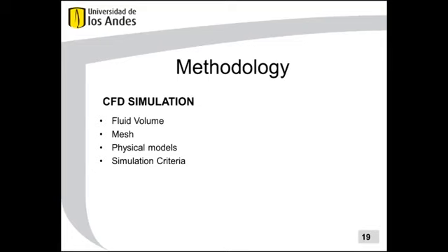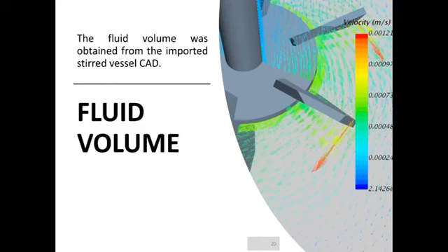Simulations were carried out in STAR-CCM+, a computational fluid dynamics software. The setup consists of specifying the fluid volume, building a mesh, establishing the physical models, and refining some simulation criteria. The fluid volume was obtained by extracting the impeller from the vessel.